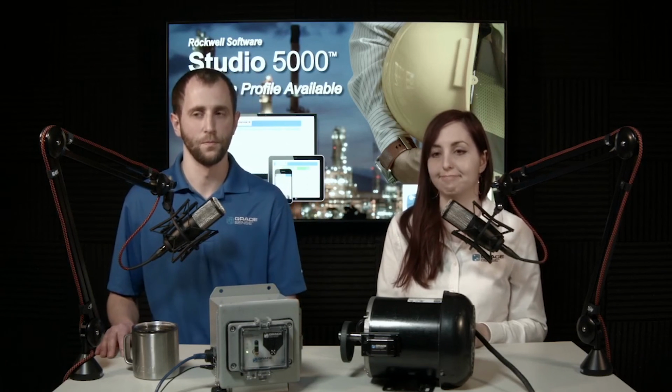And then there are also gearbox applications. If we're talking about a motor that spins at 1800 RPM and has 25 teeth on the input shaft, that would be a multiple that we'd want to monitor. And then you actually take the multiples of that. So both 1 times the gear count, 2 times, and 3 times are what you would monitor. That's definitely a key part of where the VBT2 comes into play.